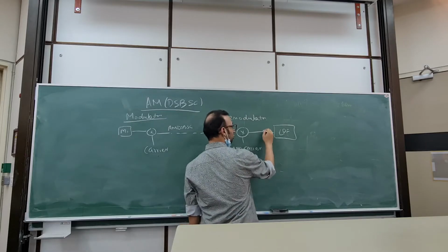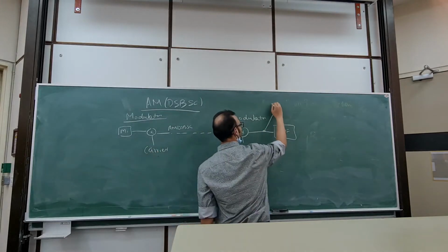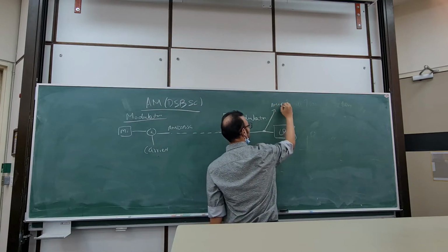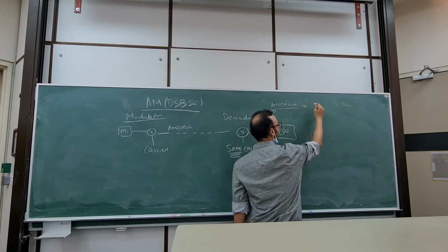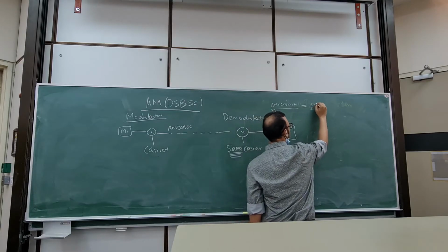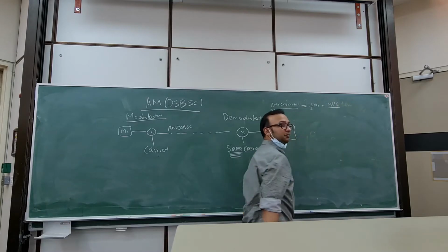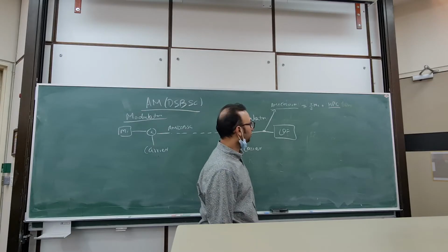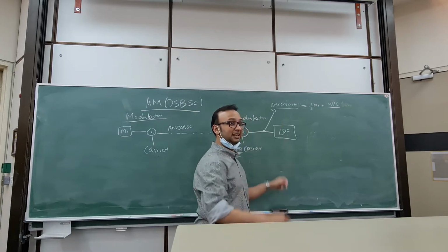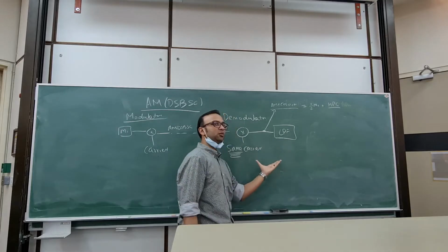The best way to know why you need a low pass filter is if you just multiply the AM signal with cosine omega CT, you will see that at the end you have half M1 plus a high frequency component. The rectifier was for when there was DC. So in the exam this can be asked: explain why you do this.